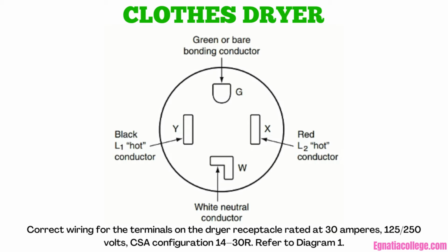Cords and receptacles rated for a higher current are available. The L-shaped neutral slot of the outlet does not accept a 50 ampere cord set. The receptacle must be flush mounted, if practical, according to Rule 26-744-9. The outlet will fit a 119 by 54 mm square box. Make sure that the box is mounted in the proper orientation to ensure that the appliance cord hangs down and reduces strain on the receptacle.